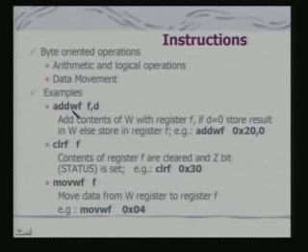When it executes, what happens? The contents of register W is added with register F, and if D equal to 0, the result is stored in W, else the result is stored in the register F. In fact, D is indicating your destination bit, which we had discussed in the instruction format. So actually when you will be using this, you will be writing it in this form. So this actually represents a memory location in the bank, and this memory is part of the PIC chip itself.